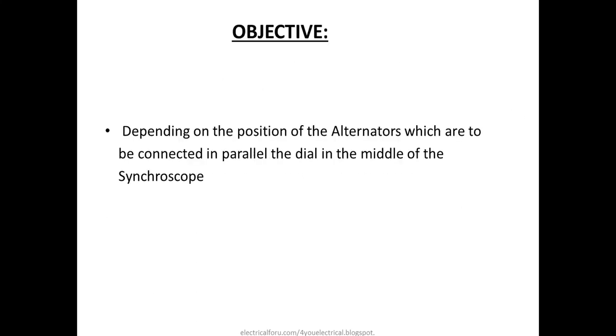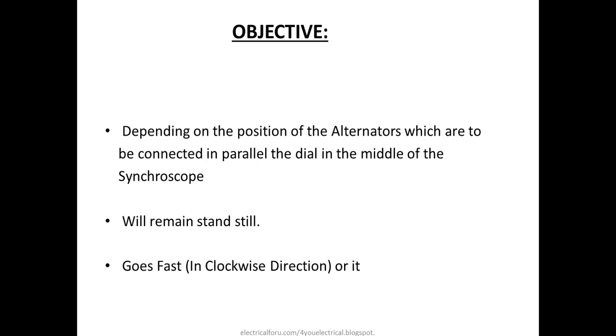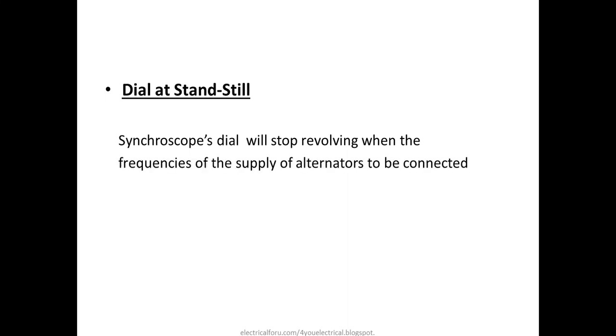So depending upon the position of the alternator which has to be connected in parallel, the needle of the Synchroscope will remain at standstill, go fast in the clockwise direction, or go slow in the anti-clockwise direction. The dial stops revolving when the frequency of the alternators to be synchronized and paralleled is the same.